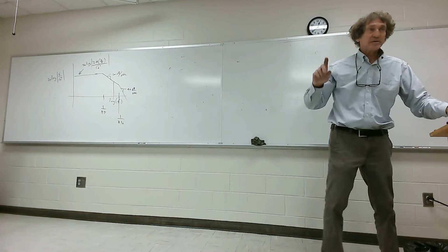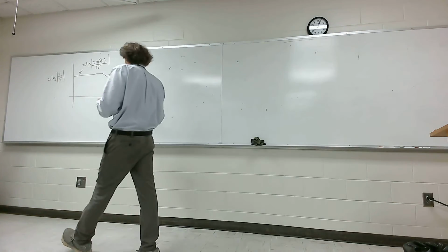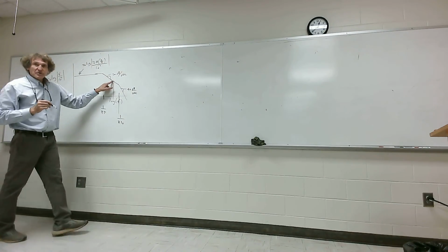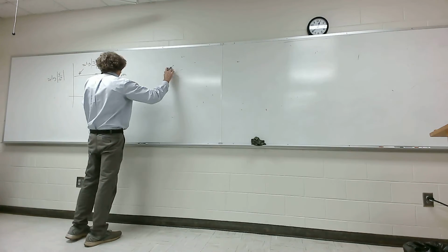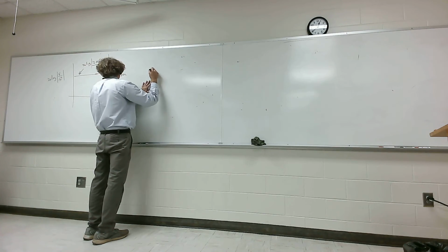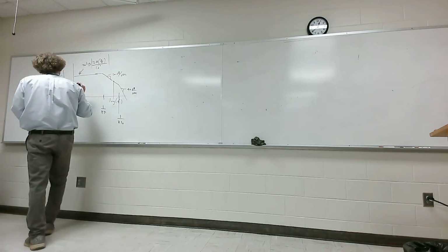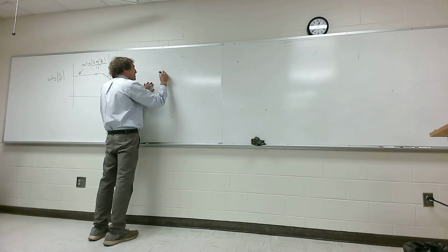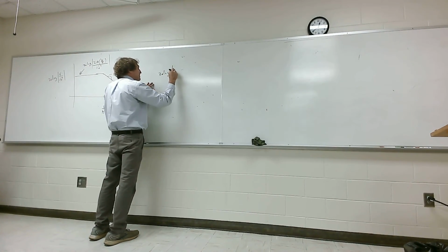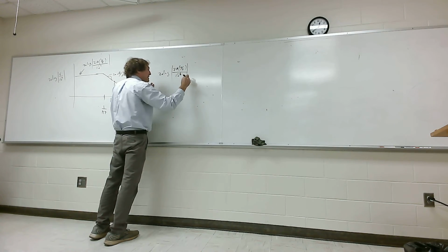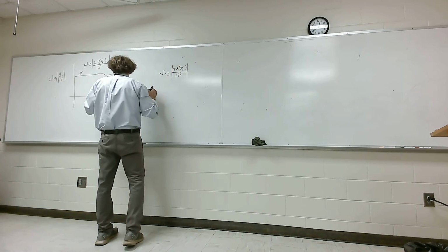So, this is an approximate method. Hang on for 1 second. Let's just say I want to know the value at this frequency right there. What I would do is say that value will be equal to the value here. So if I wanted to know the magnitude of this output, it would be 20 times the log of 2A tau over T over 10 to the minus 6.